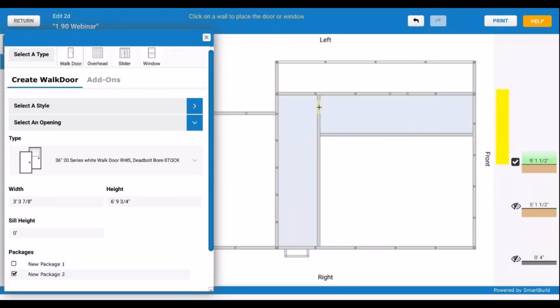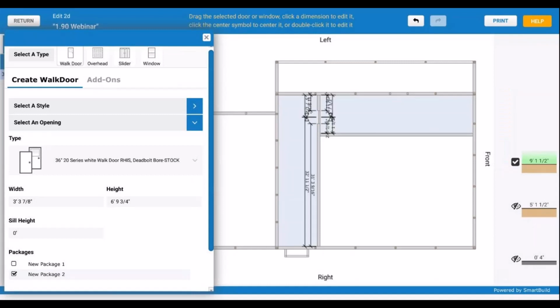You can input your doors and windows like we've had. And we do get an indication of where this door is going to be, again with the yellow. So if I just click here, we can do a similar kind of thing where you get this, and we could manipulate these dimensions. A little bit hard to see, but if we click on this, it's going to center in that wall, but then you can do things like drag, and I want to put that there.